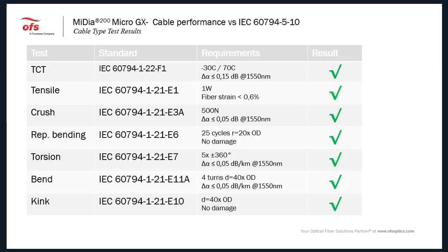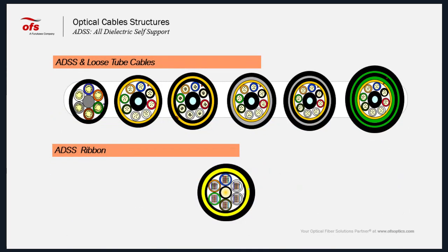So we talked about a way to densify the cable, optimized for the civil work. Now we will talk about a cable type or cable structure that allows us to deploy very quickly because we don't dig into the ground; this kind of installation is aerial. That's why this method is very widespread, especially in Africa. It's very common in Africa to use ADSS cable, all-dielectric self-supporting.